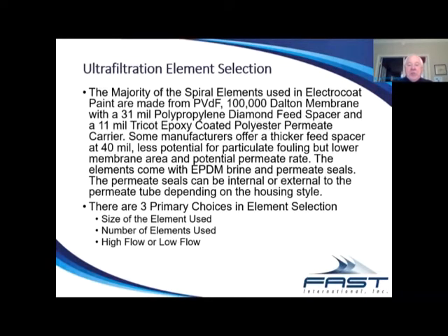Typically, all of the rubber seals that are used in this industry are EPDM, and that is the brine seals as well as the permeate seals. And the permeate seals on the element can be interior to the element, inside the permeate tube, or they can be exterior to the element, where the seals are on an extension of the element. So there's really three choices at this point in time.